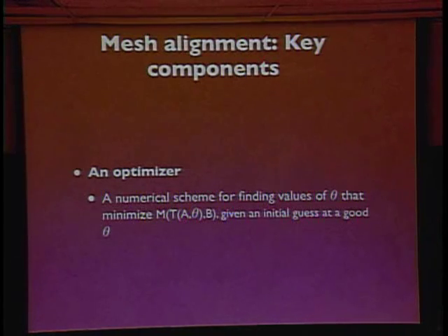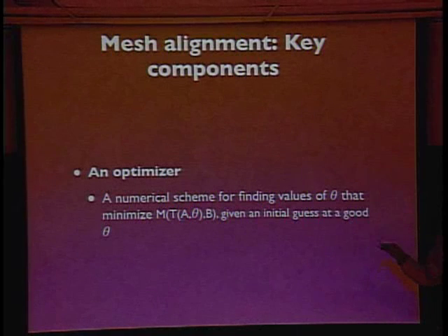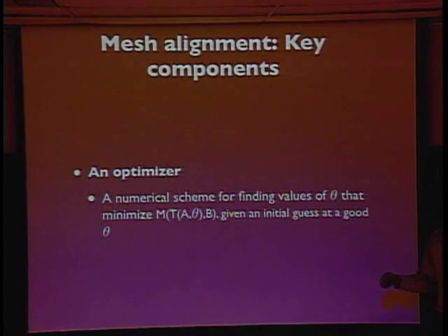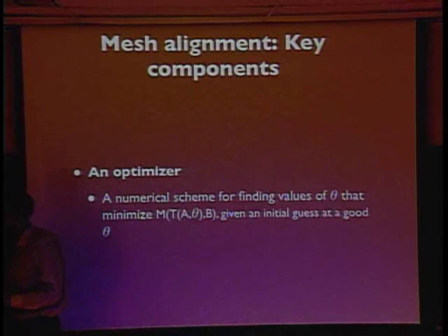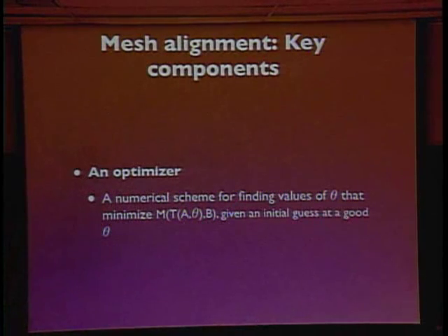And basically, imagine that you align your surface data to that larger map at one location and then drive a little bit and want to do it again. Well, from the odometer, you can get a sense of how far you have traveled in between those two. So based on that, you have an initial sense of what the geometric transformation might have been from your original mesh that you started with to the current one, in case you wanted to align those two together.